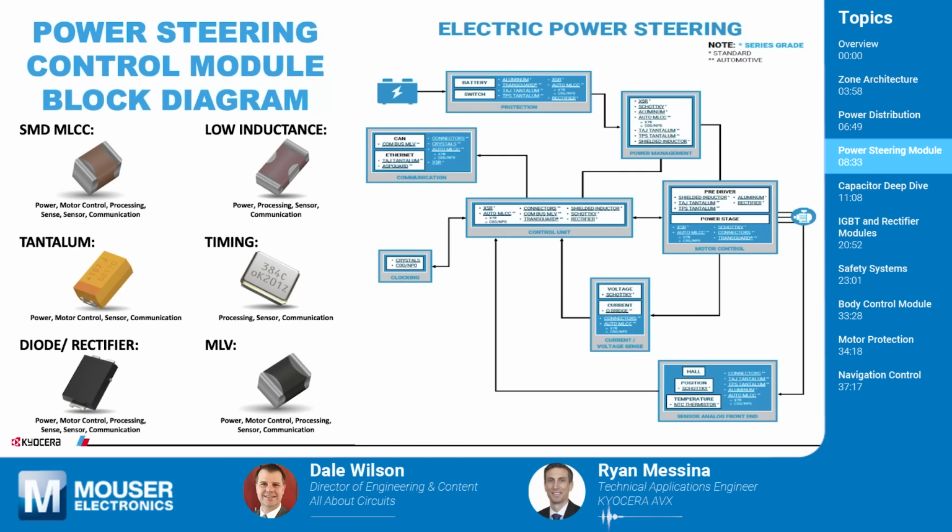So in theory, yes, you can use your commercial grade, your standard grade MLCCs or parts in general. And some manufacturers, I'm not pointing any fingers, will utilize them. And most of the time they'll work perfectly fine. But we would always advise that you go with an auto-qualified part for a vehicle. One, because you have kind of like a chain of custody, right? When you have an automotive qualified part, if there are any changes to the designs of the parts themselves at all, you would have to be notified.